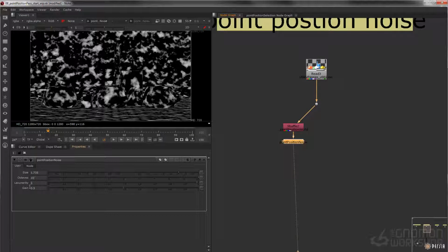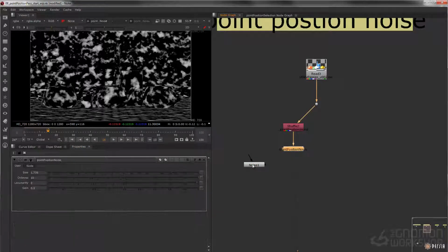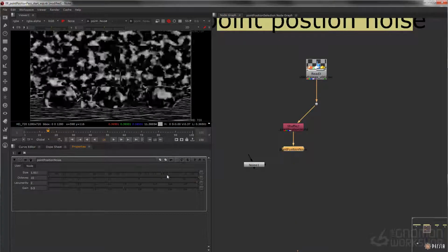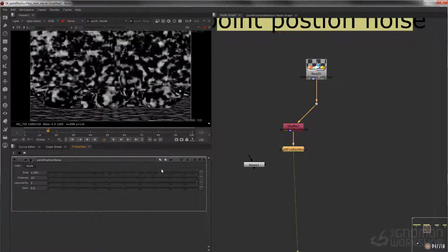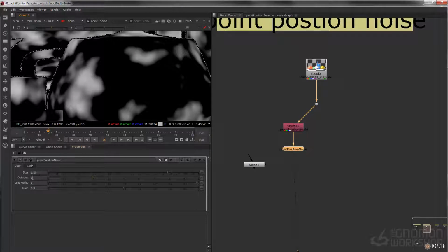If you're wondering what these all mean, they're actually coming from the original noise gizmo. So we got things like octaves, lacunarity, gain, all that stuff. All that stuff is pulled straight from the noise gizmo itself. So we have size here, which controls the size of the procedural noise. If we left click here in between our 1 and our 0 on our octaves, we can middle mouse scroll up and down to control this. And you can see it's kind of adding this detail to our image right there along these edges.